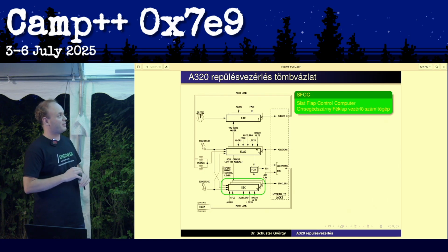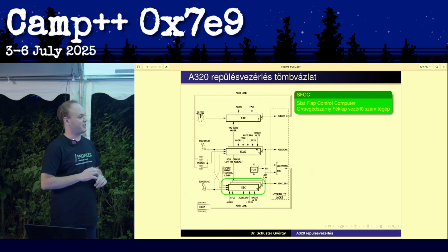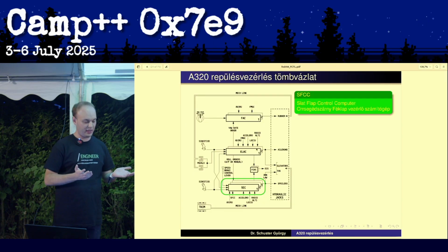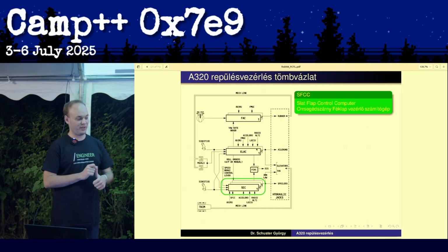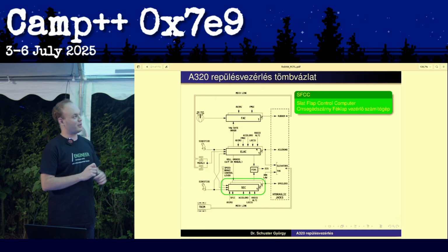So on the 737 MAX 8, of course you have two of these sensors, one on each side, but I can't really imagine how it got past all the verifications and the FAA, but somehow they only used one of their signals to detect a stall.